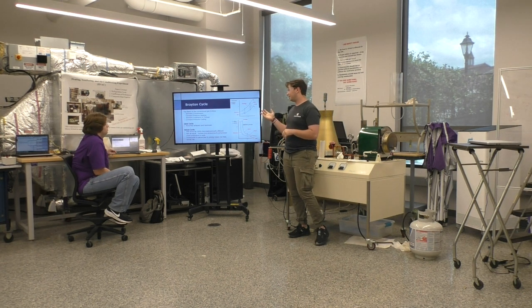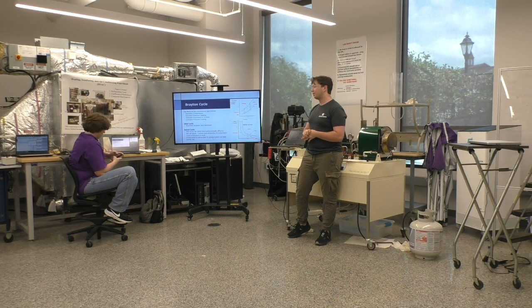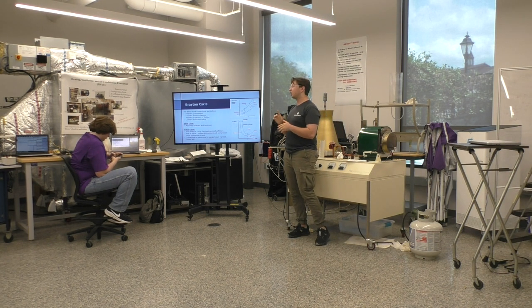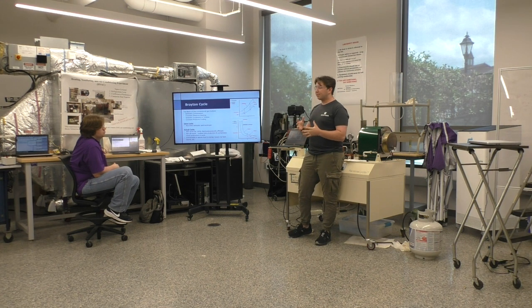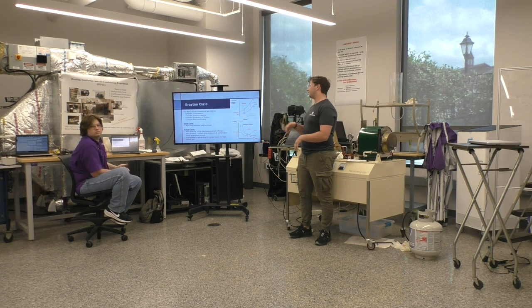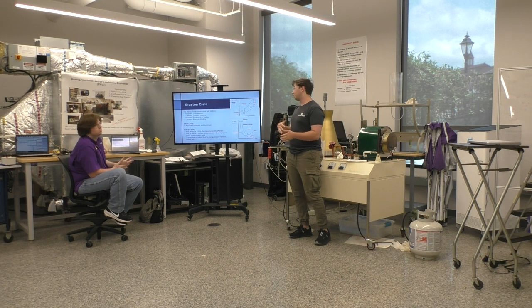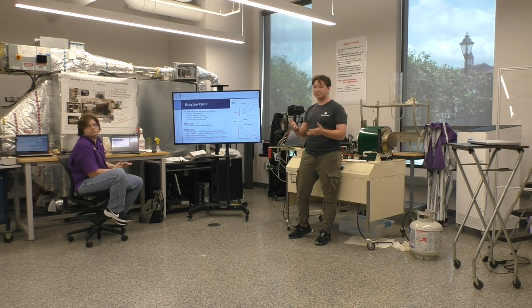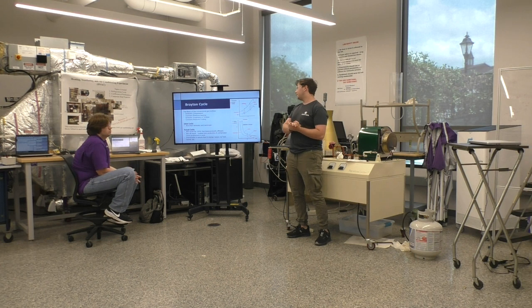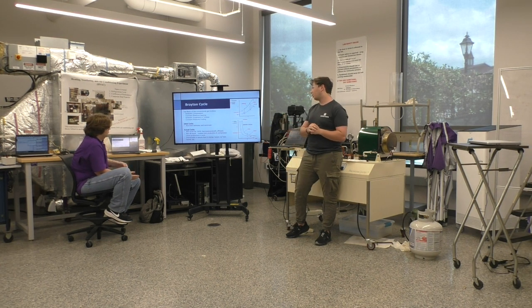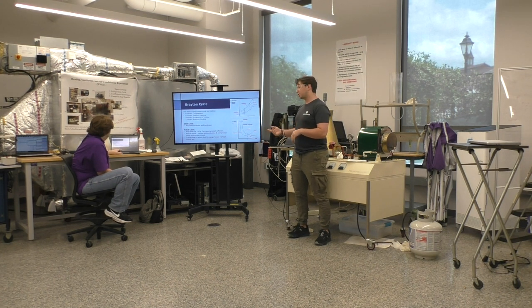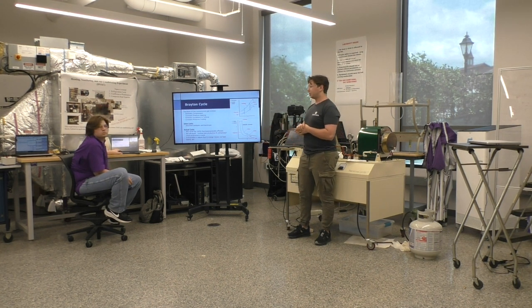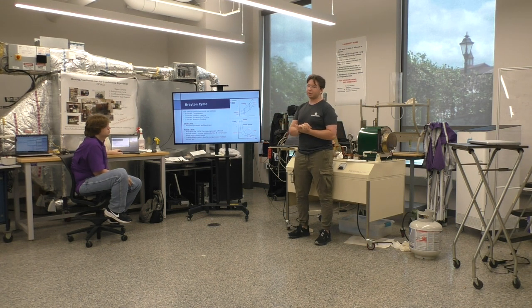Like I said, they are two different things. So in the actual cycle, it's not going to be 100% thermodynamically efficient. The turbine's going to be a little less work productive, whereas the compressor's going to be a little more work productive. So there are some inconsistencies there. And then as I said, because it's not 100% efficient, it will be irreversible due to energy loss via heat, via sound, due to the inconsistencies in the work production as well. So that's something to keep in mind.